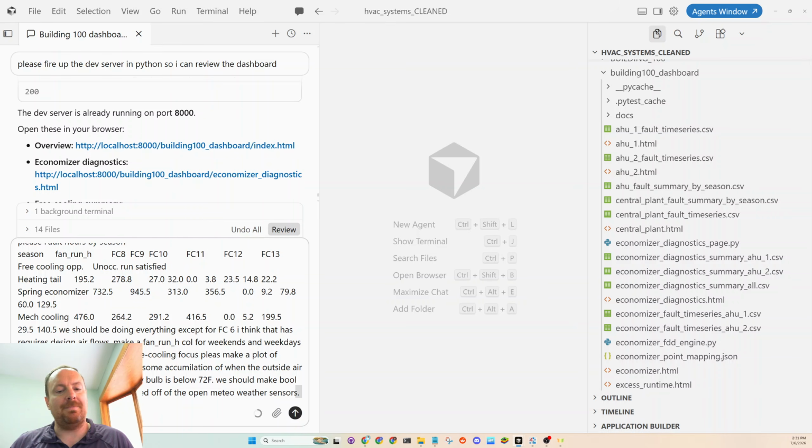And anything that's outside of what the manufacturer recommends, just a couple years maybe, you probably may not want to leave return air enthalpy control because it requires calibration. So we went off of a weather web station dew point, where if the outside air dew point is below 60, which is pretty safe, and the dry bulb is below 72 as a high limit, we were calling that free cooling is available.